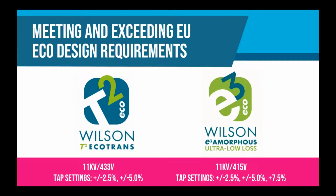Whereas the Wilson E3 will have a voltage ratio of 11 kV to 415 volts, and the tap settings will be minus and plus 2.5%, plus and minus 5%, and in addition plus 7.5%. Obviously, we can custom make transformers for you with different specs, and we've done that in the past, and you probably already have purchased special transformers from us.